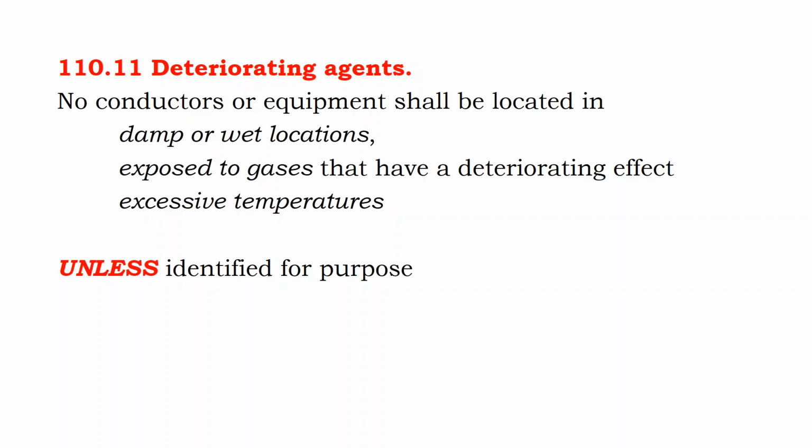Okay, so flooded lead-acid batteries and any other kind of battery that requires watering maintenance. Nickel cadmium would apply to this as well. I call them flooded lead-acid type batteries. Any batteries that you need to water as part of your maintenance process are going to emit a corrosive gas. So there's a common requirement for battery rooms where you have to put your batteries inside a vented room. Often you're putting batteries in an air-conditioned room that has an air vent in it. And so is that air-conditioned room a vented room?